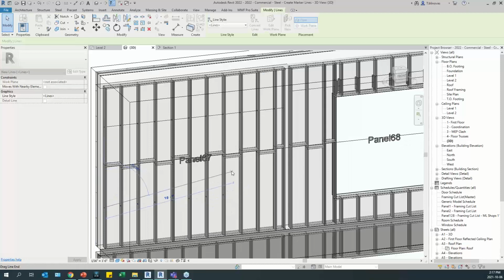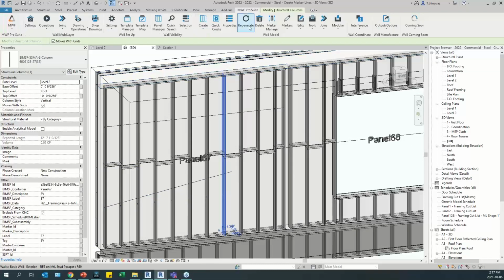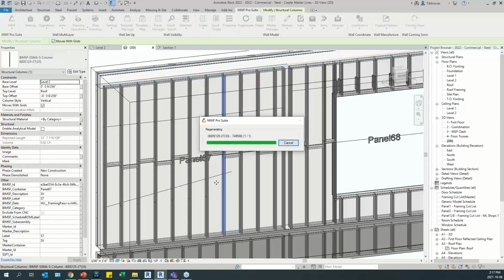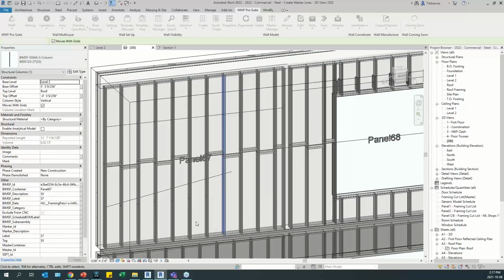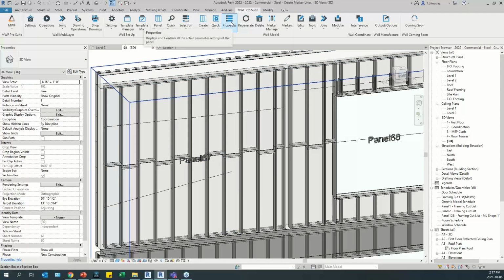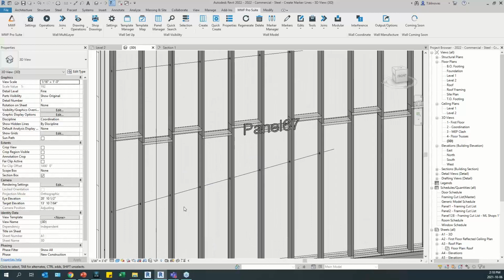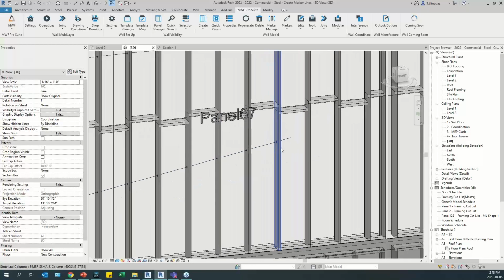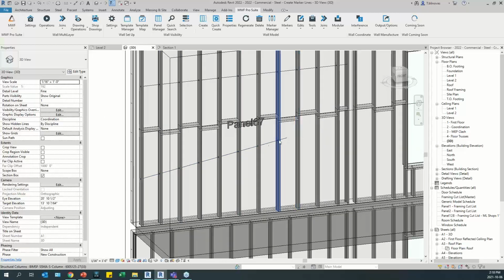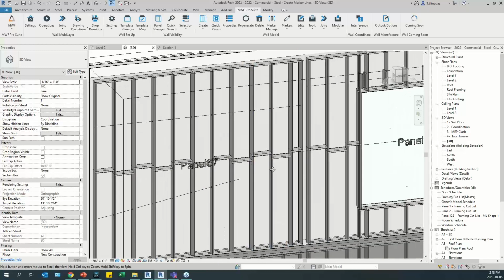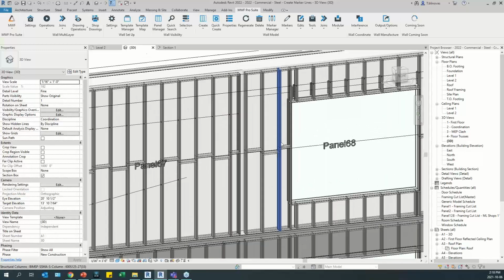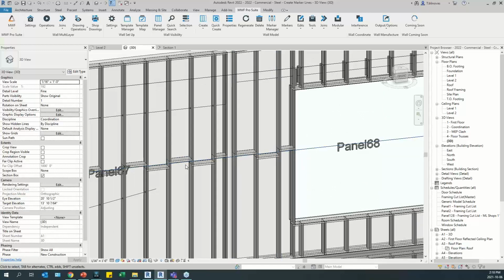Let's say we add this at an angle, for example. This is supported by the marker lines, but it's not supported in the option that we have within properties. This would be very difficult to achieve when you add whole series in properties. But if you're using marker lines, you can simply move them around and it will always follow that change. So that would be a good idea in case you need an angle like that with your punches, or if you need advanced cutbacks for your blocking.